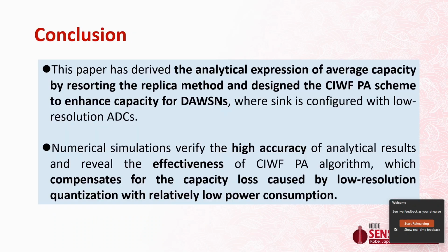This paper has derived the analytical expression of average capacity by resorting to the replica method and designed the CIWF PA scheme to enhance the capacity for DAWSNs, where the sink is configured with low-resolution ADCs. Numerical simulations verify its high accuracy and reveal the effectiveness of the CIWF PA algorithm, which compensates for the capacity loss caused by low-resolution ADCs with relatively low power consumption.